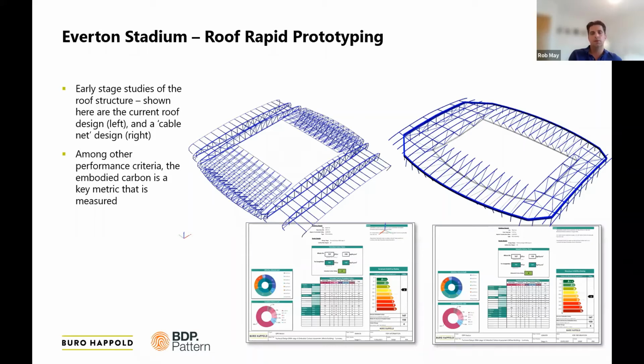And so typically one of the most efficient structures to put over a long span roof is a cable net. But in the case of Everton, the geometry is not quite what it would need to be to make the cable net as efficient or buildable. And again, that complex series of reasons why one is better than the other doesn't quite make it relevant or the best solution for Everton.